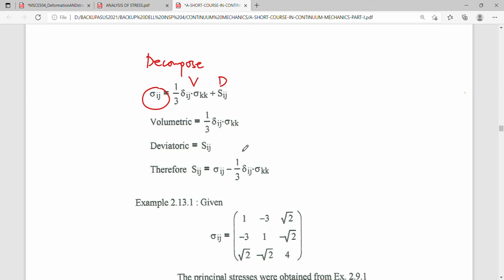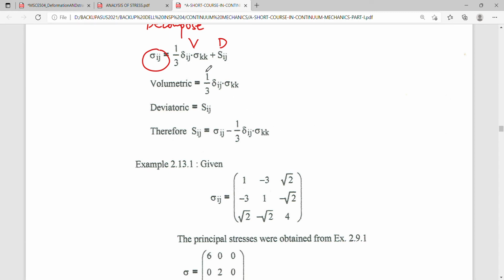Because Mase's approach is more mathematical, while Frederick Chang is more in the applied aspect of continuum mechanics. Of course, if you are trying to decompose the two, the total must still be the same stress matrix or stress tensor, such that if we now back compute the deviatoric part here, we simply subtract the volumetric from the original stress tensor, and we get this one here.